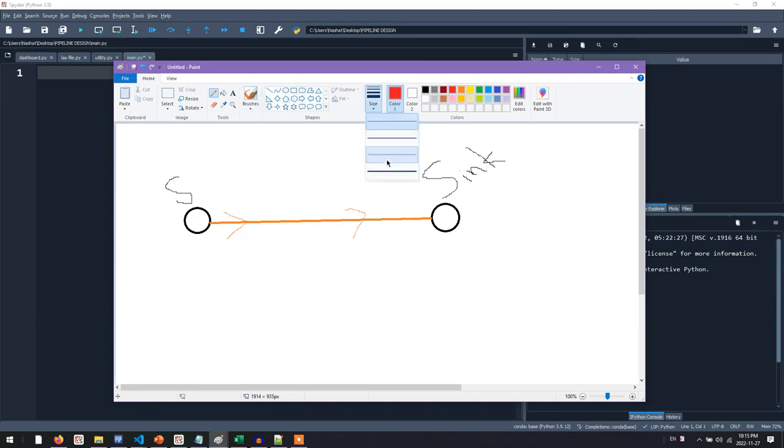We have a few points that control the flow or the flow phenomena. The first thing is the pressure at the source. We have the pressure at the source, and we have the flow rate at the source. By the way, if you have a specific flow rate, let's call it Q1, entering from the source in this direction, the same flow rate Q2 should be on the outside, meaning that Q in equals Q out. This is known as the conservation of mass.